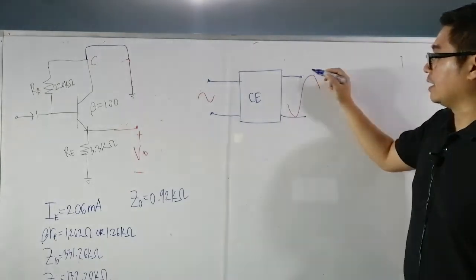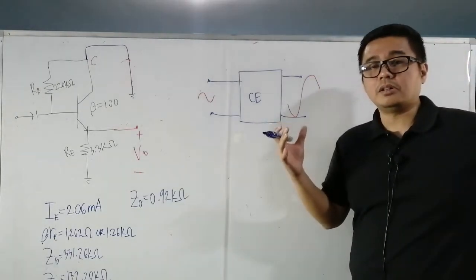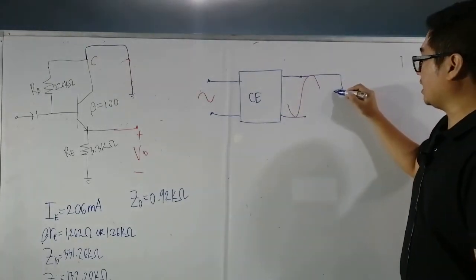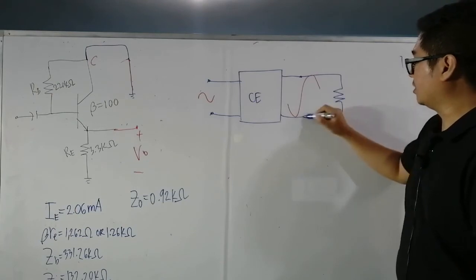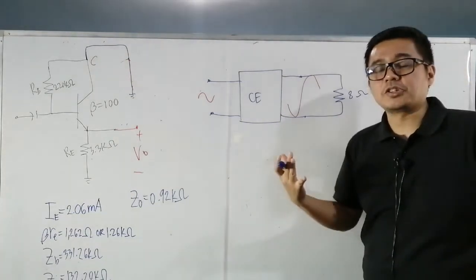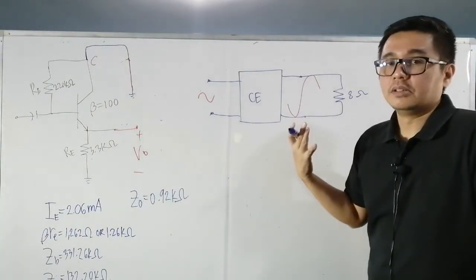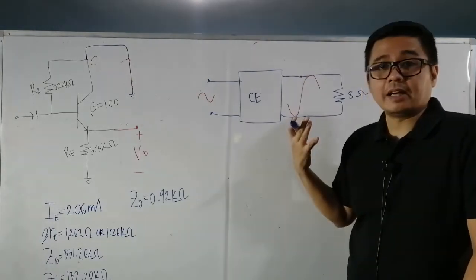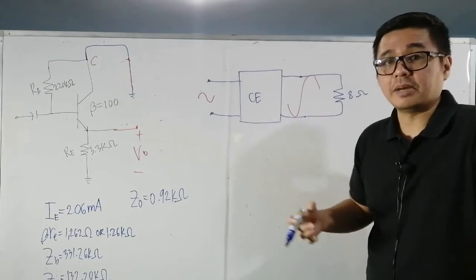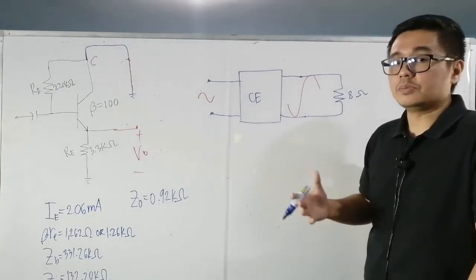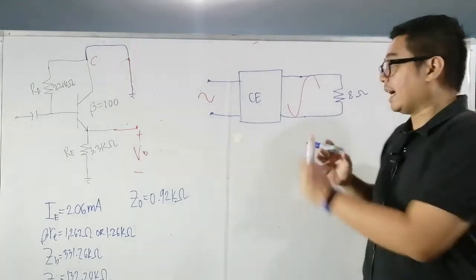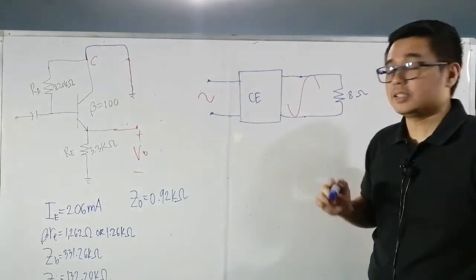What if we connected a small load, a small value ng load dito sa ating output? Let's say, yan. So maliit lang, let's say 8 ohms. No? Sa practical applications, yung mga ganyang kaliliit na load, nakikita natin sa mga audio systems. No? Halimbawa, yung load na yan ay isang speaker. So meron tayo, for example, 4 ohms, 8 ohms, 16 ohms na speaker, which is mababa. Parang wire na lang. So, ang nangyari is, almost na short out yung ating signal.